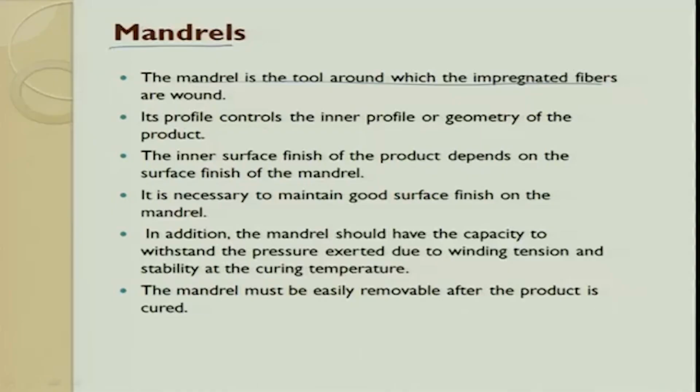Second thing is curing depends. So, its profile control, the inner profile geometry, I have told you all this point. The inner smooth surface depends upon the mandrel. It is necessary to maintain good surface finish on top of the mandrel, so that the inside of the component is maintained. So, mandrel is very, very important in terms of dimensions, material, and also they give texture to it to have better grip.